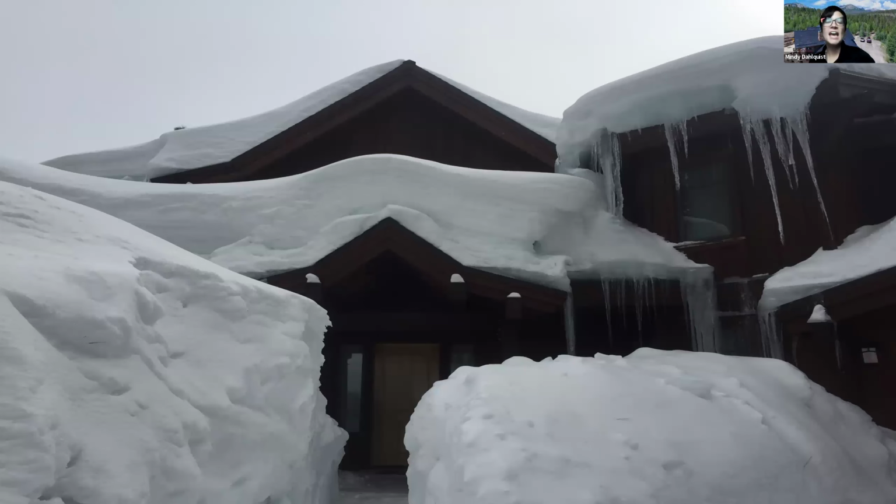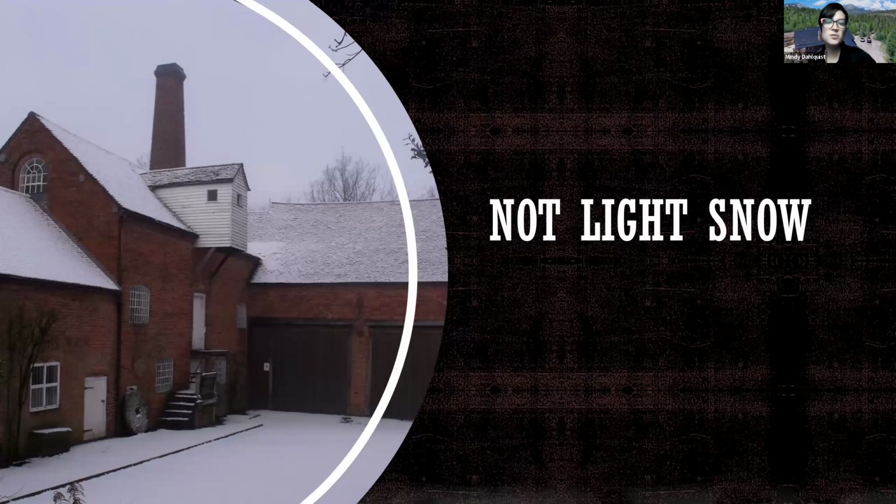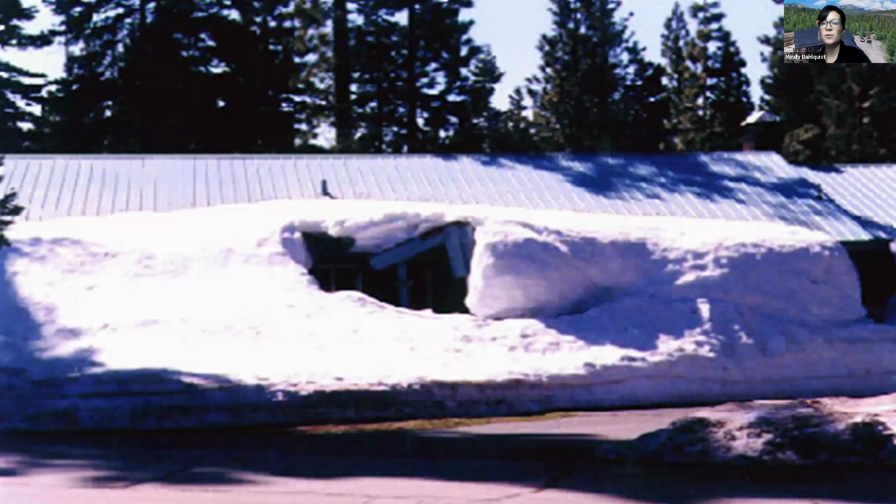So we're not looking at a light and fluffy little bit of snow. This isn't snowball weather or snow angel weather. This is massive amounts of snow. When the snow accumulates on the roof, it glaciates. So what you're dealing with is not just a couple little piles of snow up there that you can take a broom and just hit them down. And the goal of snow retention is not to break that snow up as it slides. Since that snow is a glaciated mass, the snow fences and brackets are utilized to help protect that snow from ever being able to slide off of that roof surface.